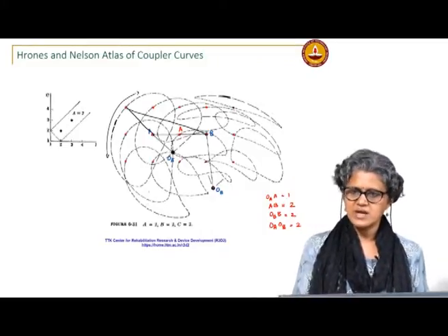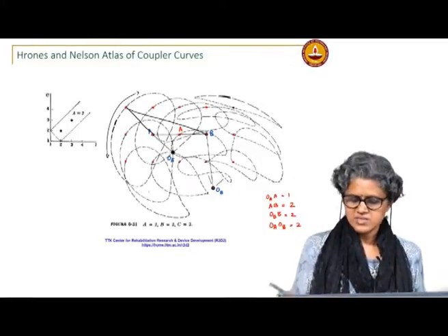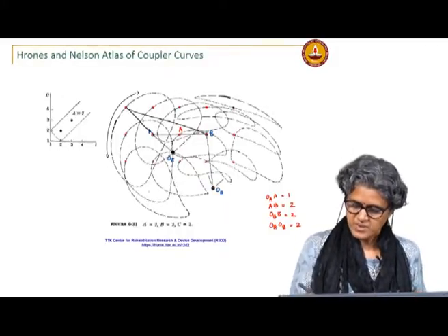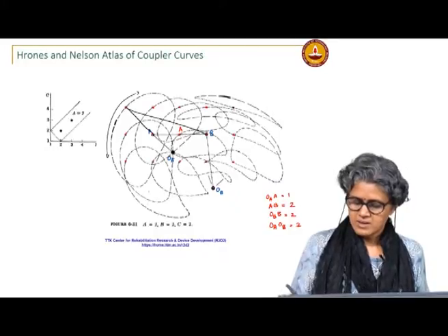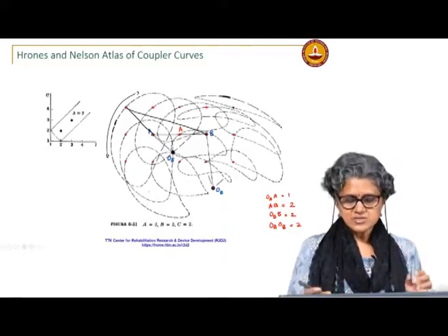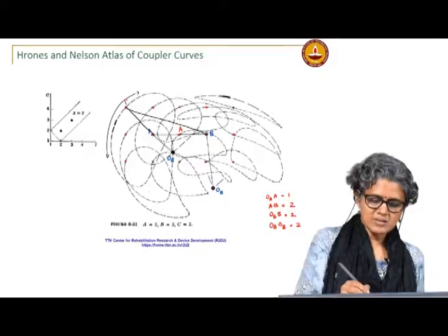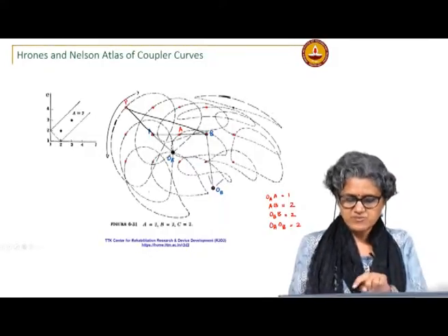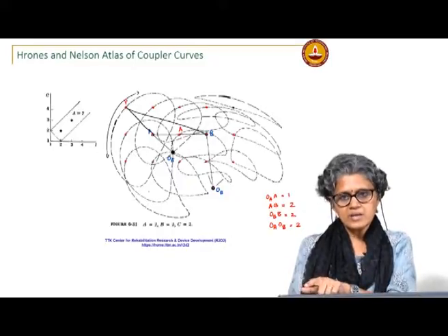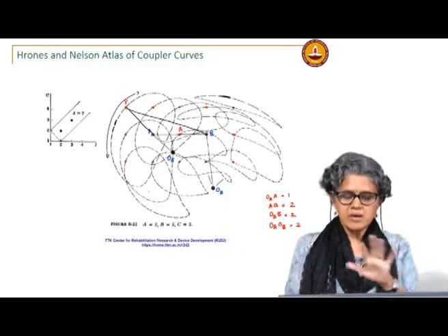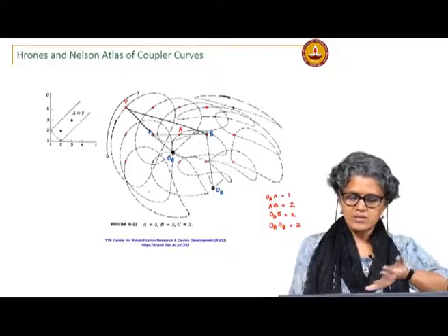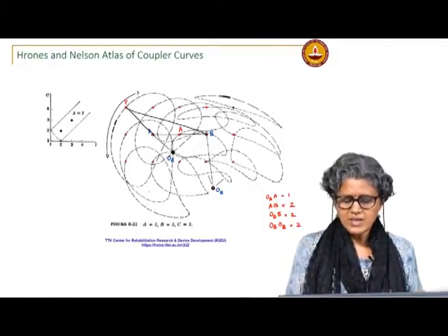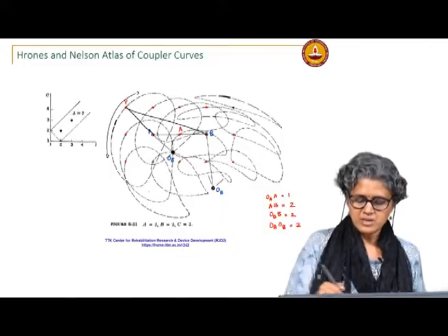You can see this is a Grashof linkage and the crank is the smallest link. So, it is a crank rocker. So, I can now try to scale it. I can now measure the location of this coupler point P, and from this, scale it up accordingly. Okay, it will be an approximation, but you can get pretty close. The coupler curve that you will get will be close to that.